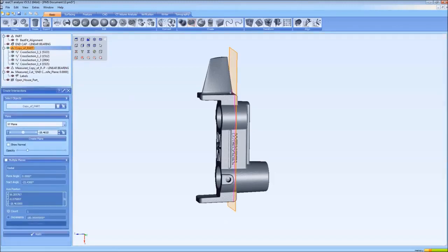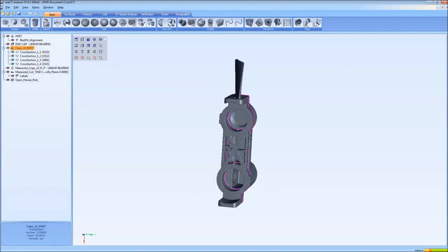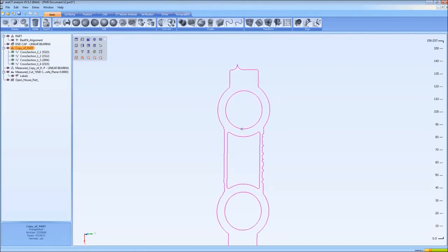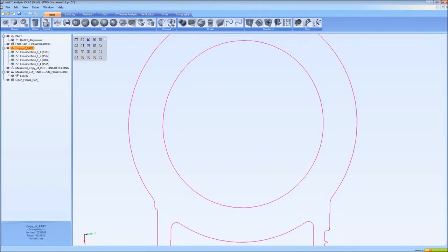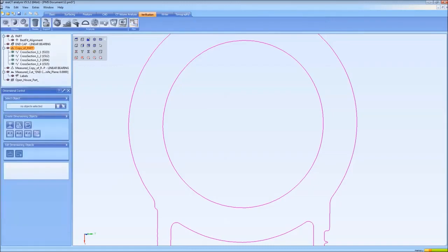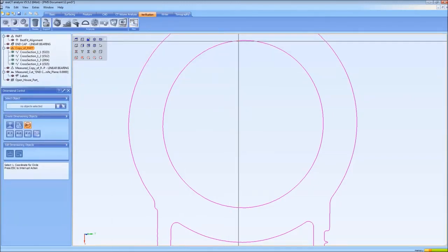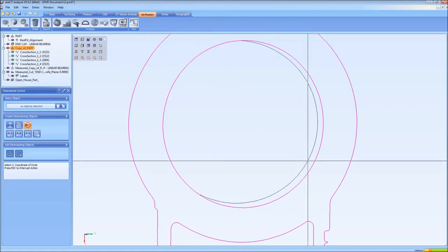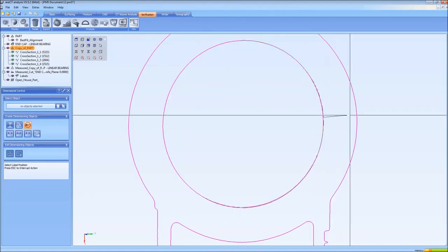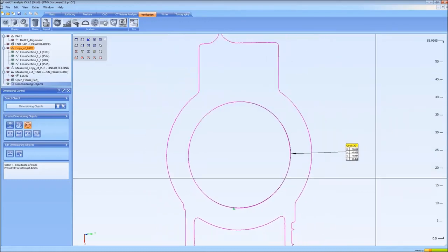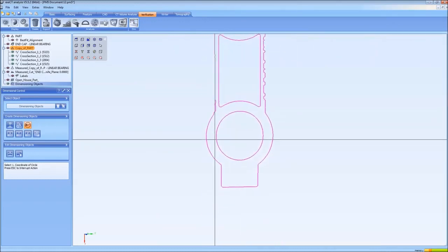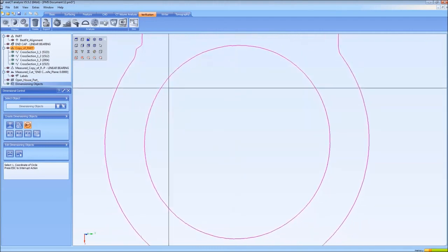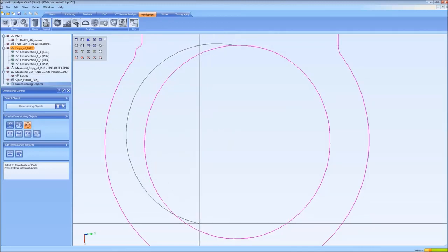The PointMaster is a very modular software. It can be configured for any kind of application with the modules. Here we see some applications now. In this case, we have cuts. We can perform virtual cuts through the part and can do a dimensioning of the inner geometry of the part. Here as an example a circle, but there can be circles, angles, distances, whatever.